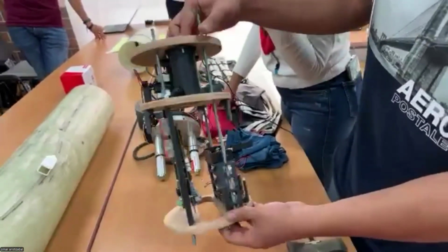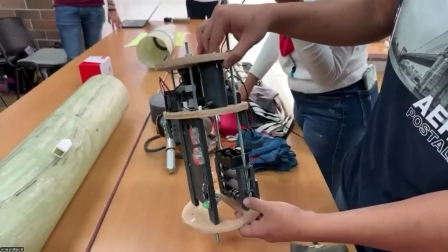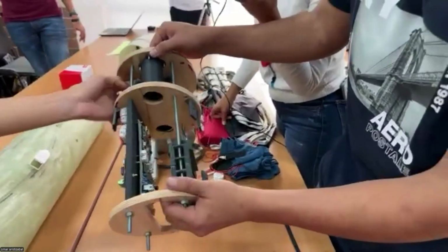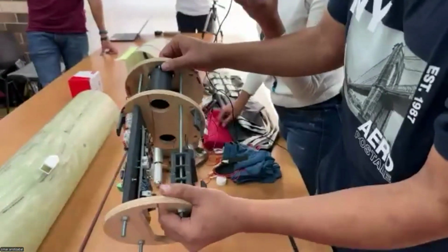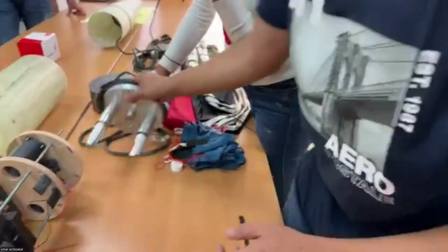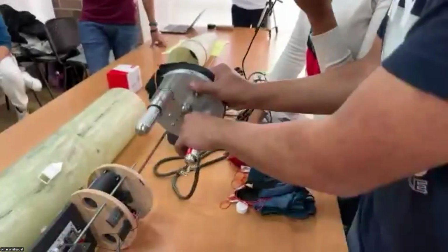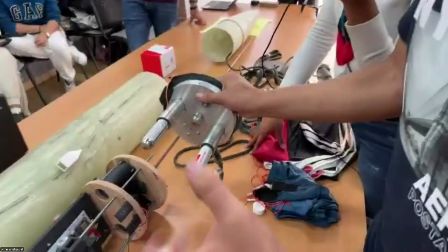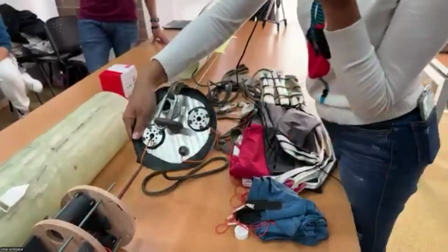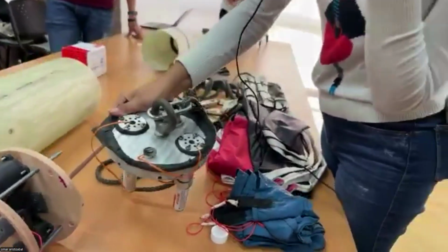Do you expect to see any force from your ejection systems on your avionics bay? No. We are not expecting to transmit any force into this avionics section, because, as I said, these ejection bulkheads, including the other one placed here, are completely independent structurally from the avionics section. They just sit around each other, basically. Okay, that's good.